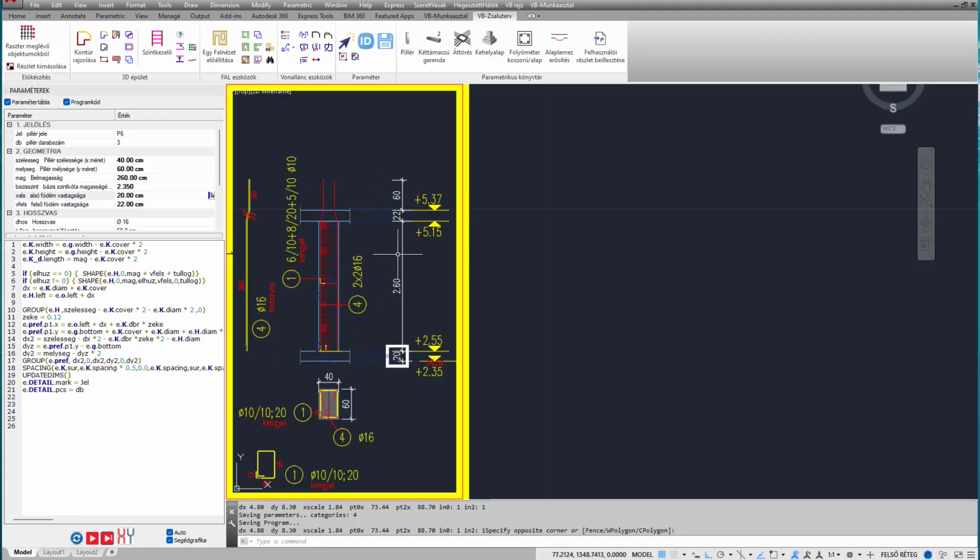Obviously, the predefined nodes I create may not suit everyone in terms of reinforcement or appearance. But because everything is controlled at the style level, it makes sense to adjust the display in our own drawing by setting the assigned style the way we want it. If that is still not enough, we can modify the node and then save it as a user detail, which can later be loaded just like the so-called factory details.